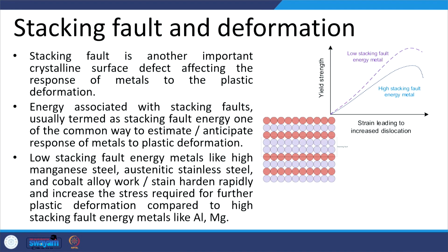Stacking fault energy is about the arrangement of the atoms which is defective. So, the stacking fault is another crystalline surface defect affecting the response of the metal to plastic deformation. If we see this diagram here, we can see there is an arrangement of a particular order of the atoms, but in this particular zone this arrangement is disturbed.